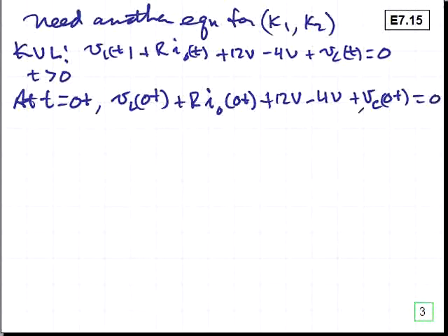Now we said we assumed the initial condition on the capacitor was 0 since we had no other information. So we'll drop that out of the equation. We have an I0 at 0 plus. I0 at 0 plus is equal to IL at 0 minus by the relation of I0 and IL flowing in the same direction in the same inductor and continuity of the inductor current.